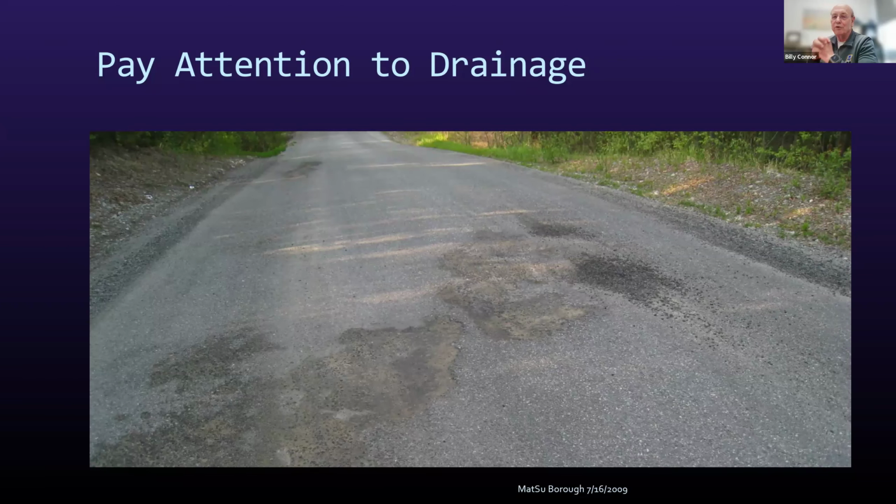And we've talked about drainage throughout this discussion, trying to reinforce that drainage is critical to everything you do. But once you start putting hard surfaces on there, it becomes even more critical because now you're starting to lose pavement that's very expensive surfacing, and you have to replace it fairly quickly, and you really don't want to do that.